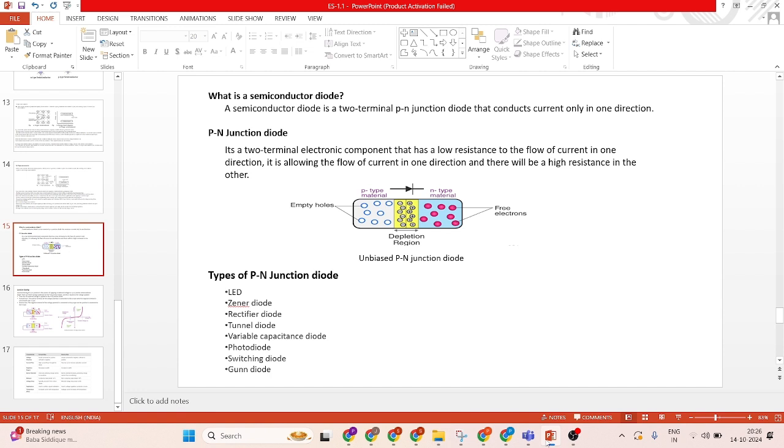Because of the attraction between electrons and holes, electrons move, so there is recombination of electron and hole pairs. Energy is lost due to this recombination process. As a result of recombination, the electrons in the N region are neutralized by the holes. Hence, ionized donor atoms carrying positive charge are left behind. This small region is the depletion region.